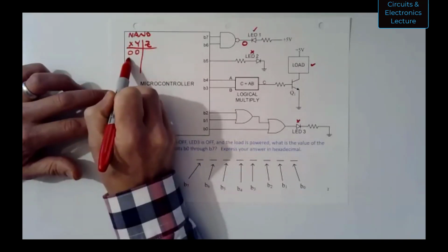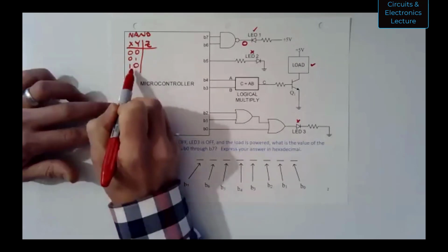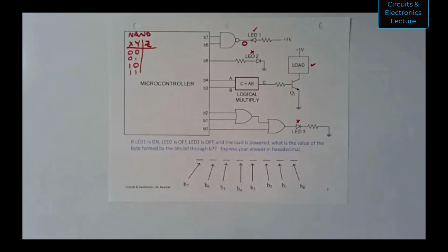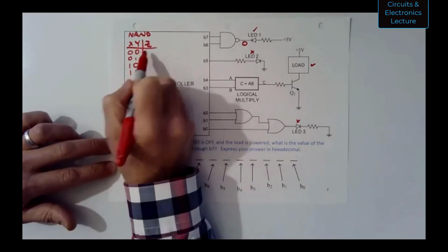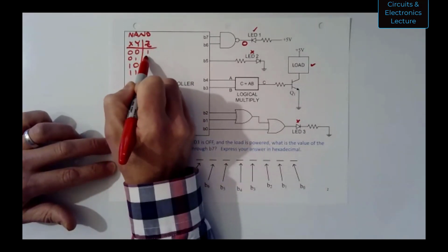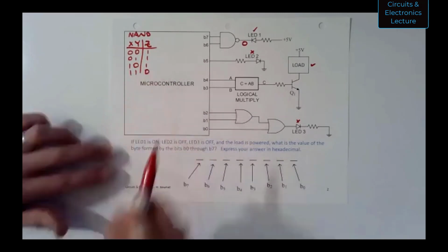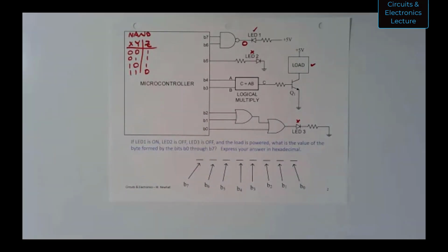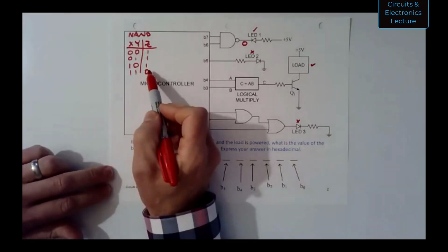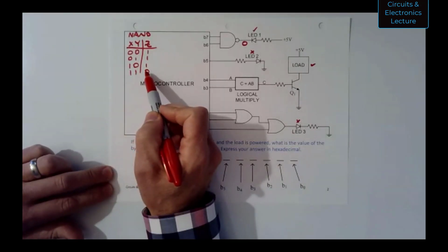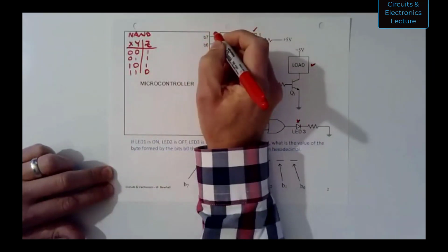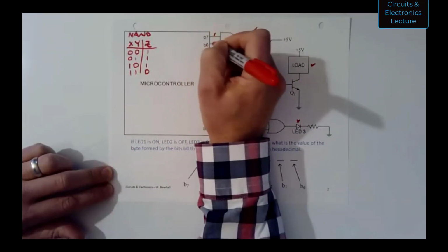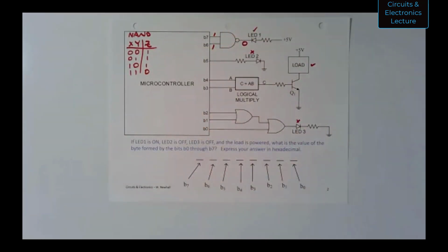All possible combinations of inputs, you could write this down, would be those. Count up in binary from 0. And the NAND gate would have this. It's the inverse of the output of an AND gate. So the only way you get a 0 at the output of a NAND gate is to have both inputs equal to 1. Okay, so I'll write those values there.